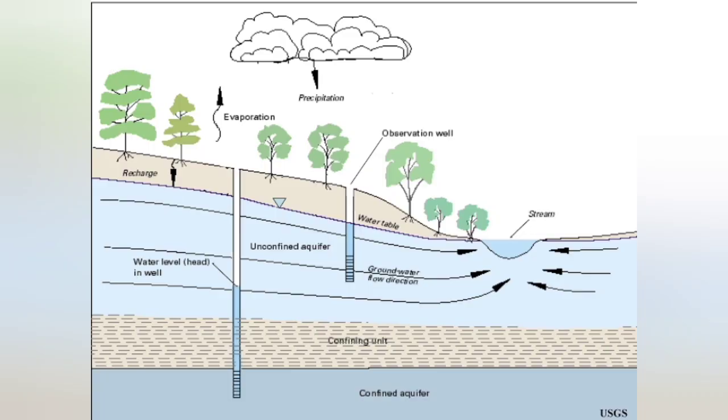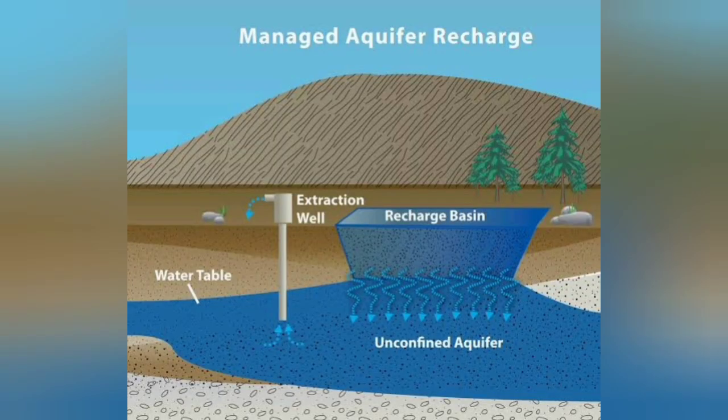Infiltration in its most narrow and precise sense can be defined as the process of water entering into a soil through the soil surface. Although a distinction is made between infiltration and percolation, the two phenomena are closely related since infiltration cannot continue unimpeded unless percolation removes infiltrated water from the subsurface soil.